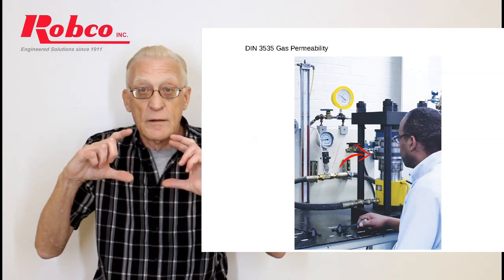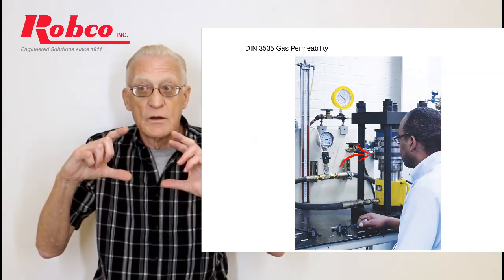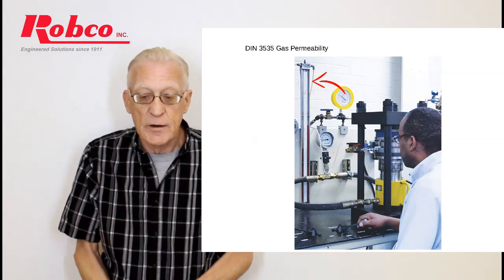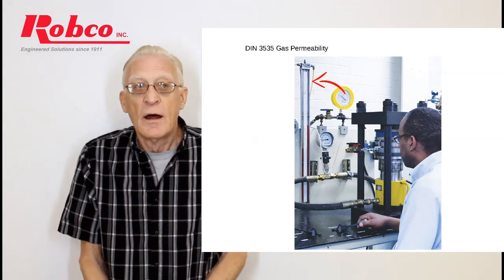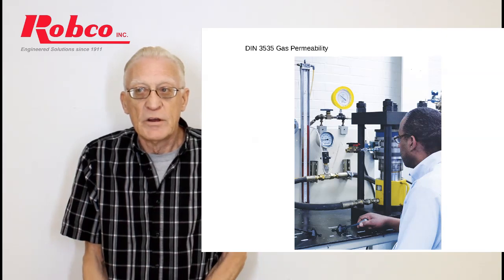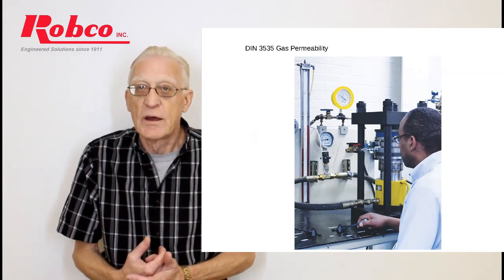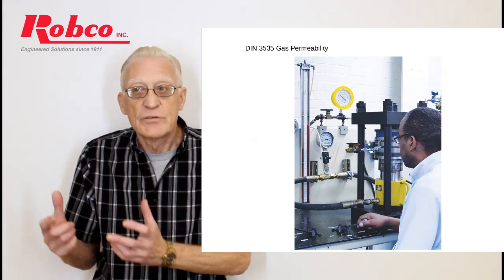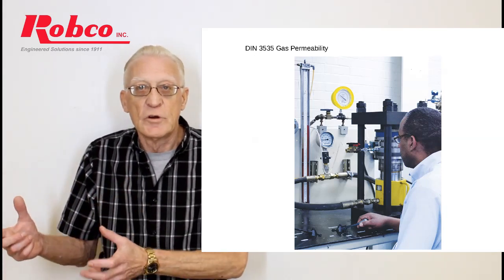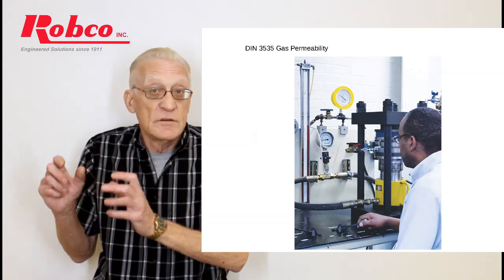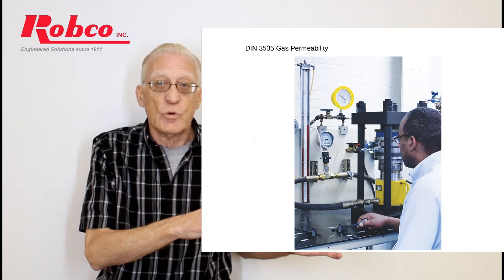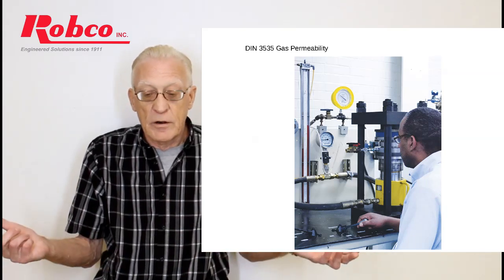So when the gasket leaks, it's trapped and it's measured on the mercury manometer on the left-hand side. The beauty of this is it will only leak through the gasket. We've gasketed our gasket. And again, if you do that microscopically, you're going to see leakage through the gasket itself. What does each material do? And you can compare.